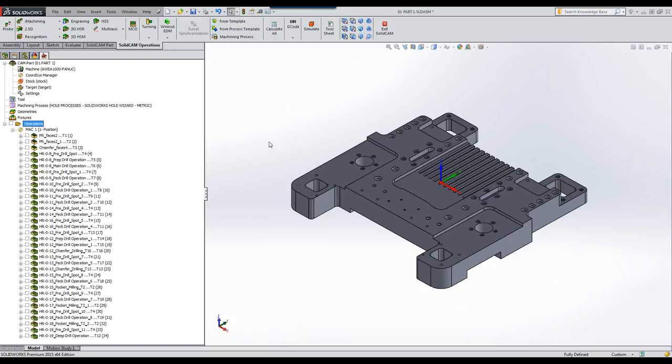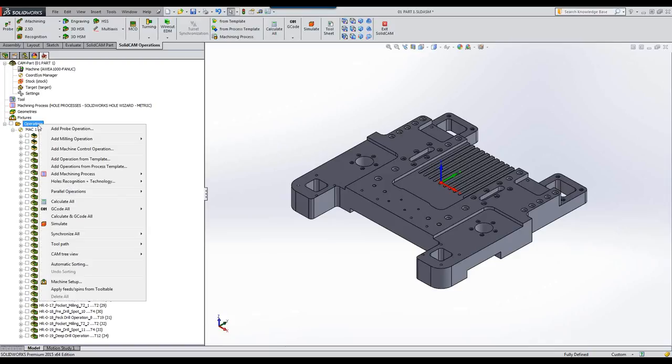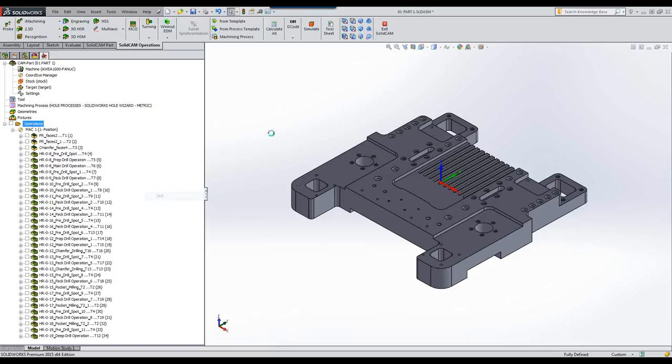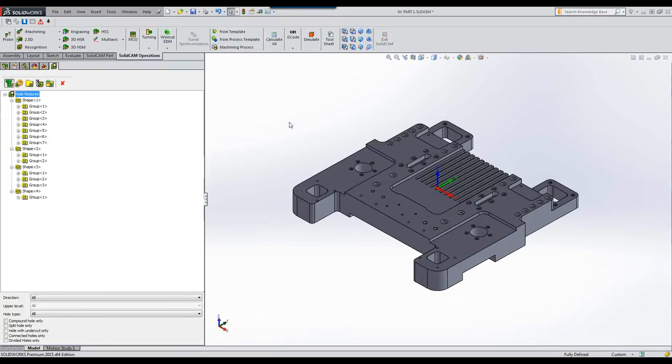The technology of how everything was done automatically inside the automatic hole recognition and machining is based on the database that was used over there. Now, what exactly is the database? Let me go back into hole recognition technology. It will go into the database itself. When I click on the option of starting my hole recognition, it automatically uses a specific database.